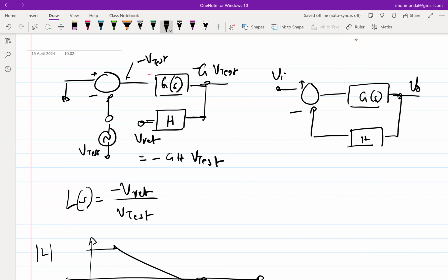we have already done it once, we have replaced the G with a differential amplifier, right? So when you have a differential amplifier and H is also loading the differential amplifier, H is a resistive divider, for example, then you exactly don't know which is G, which is H. But as it turns out, the product of GH is comparatively easier to find, right? You break the loop, apply, and then figure out what returns. The ratio negative of that is L of S, right?